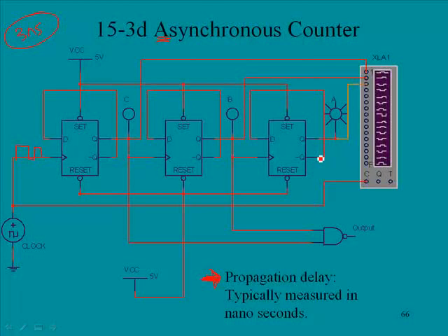And if we have a high-frequency input, there is the very real possibility that you begin to send pulses in, and before the cycle is completely clocked, a new cycle is occurring. In this case you can lose counts and it can become problematic. So for this reason, the synchronous variety of counters are actually more popular.